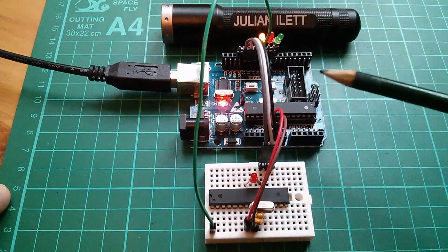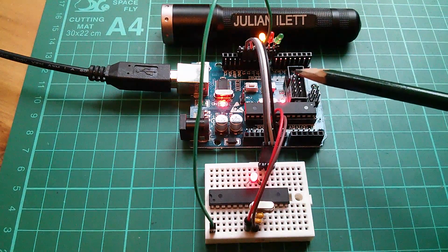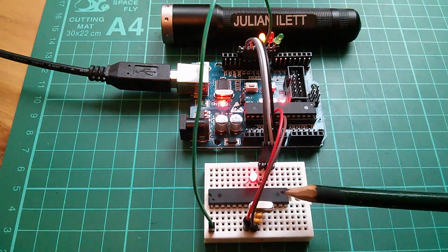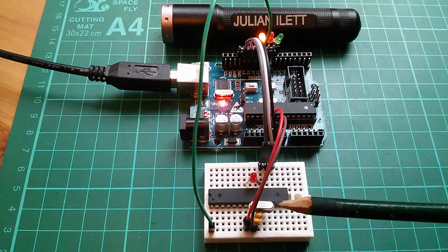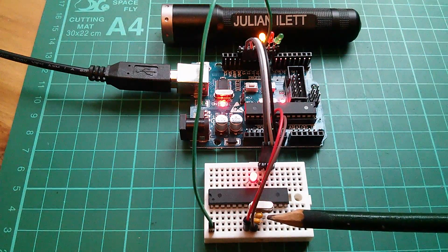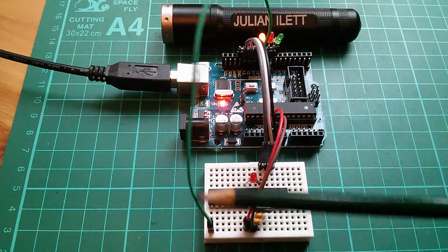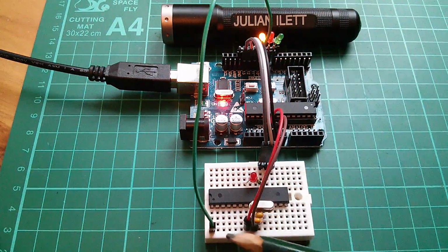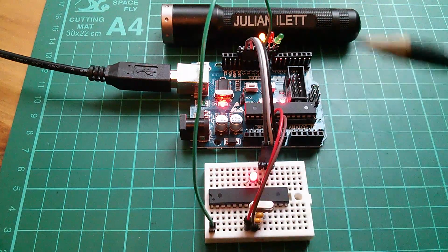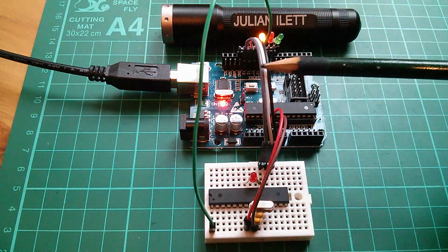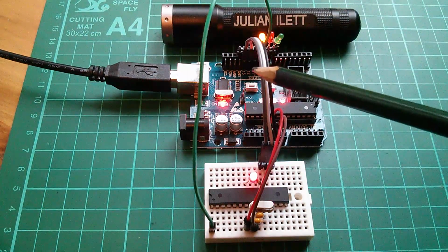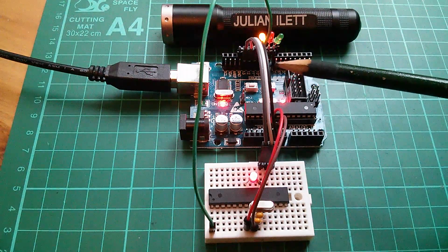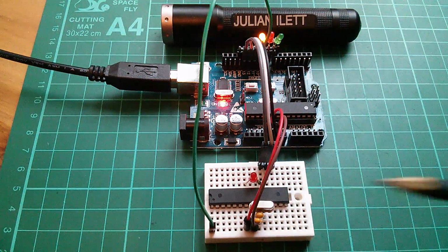So here's my setup, wired pretty much according to the diagram on the tutorial. I've got VCC and ground here powering my target system, which has an ATmega328P, 16 megahertz clock crystal, a couple of 20 picofarad capacitors. The green wire is reset, comes from pin 10 on Arduino as an ISP to pin 1 of my target chip, that's the reset pin. And then these 3 wires, I've used black, white and grey, come from pins 11, 12 and 13 on the Arduino as an ISP. They are MISO, MOSI and clock, not necessarily in that order, and they go to these 3 pins on my target system.